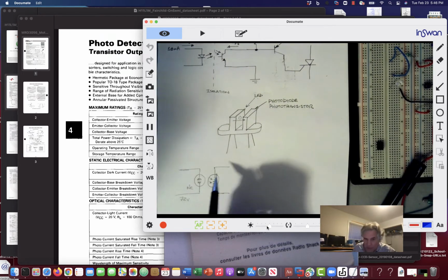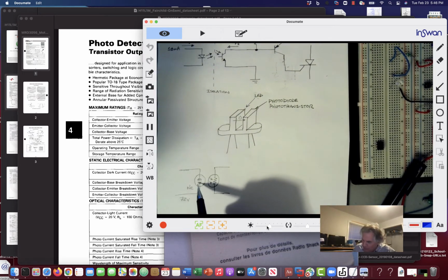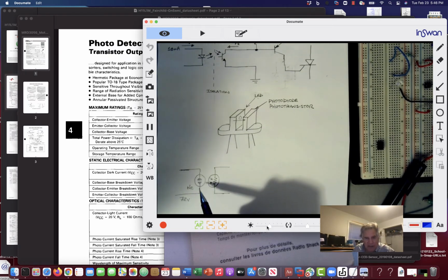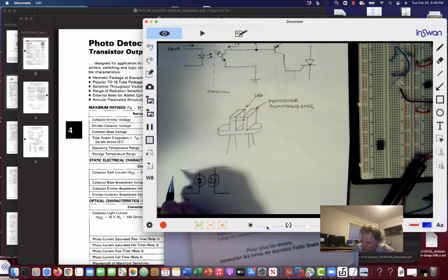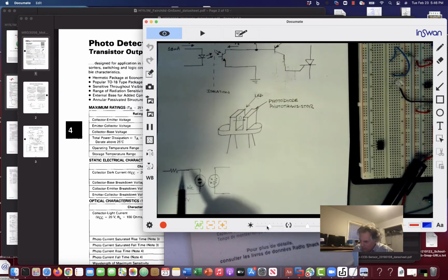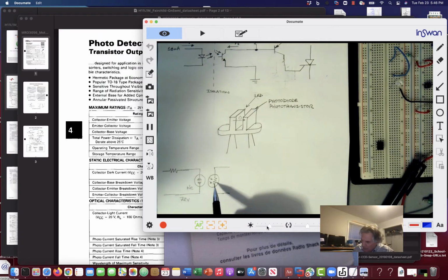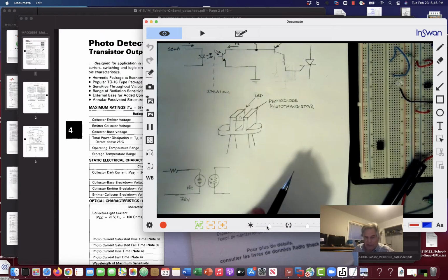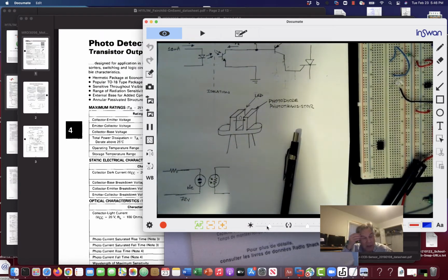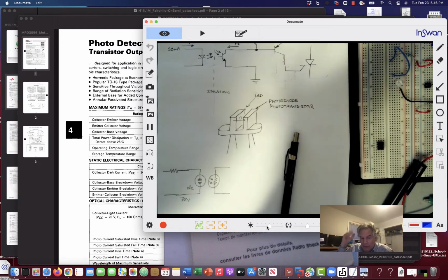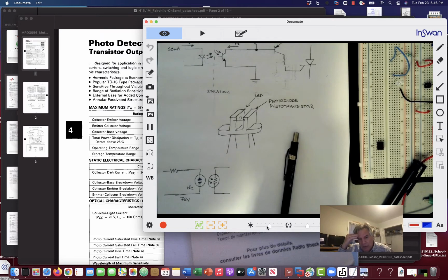But the ringing voltage would fire this neon bulb 20 times a second. And we had a current limiting resistor in here. And so this would light when the phone was ringing. We'd pick it up here and go through a transistor circuit, and it let us know that a call was coming in and that we could activate whatever we needed to activate.